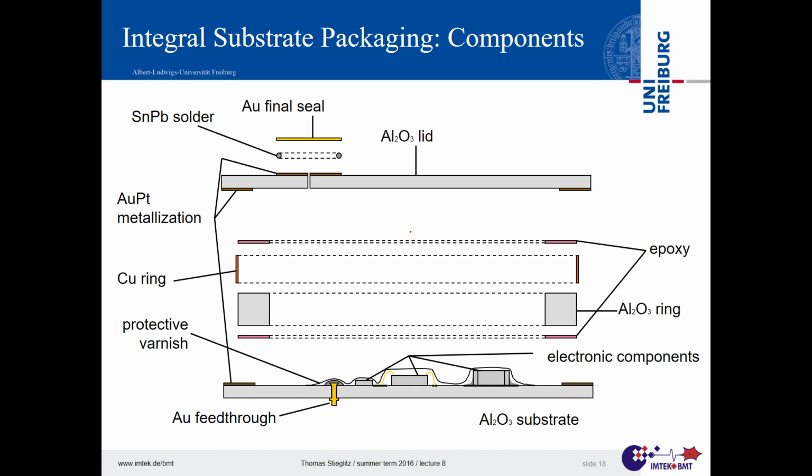And the delta T, so the temperature difference between soldering and destruction temperatures and diffusion-related processes, is smaller in most of the lead-free solders. And that means you have to play some tricks. Which one do I use?